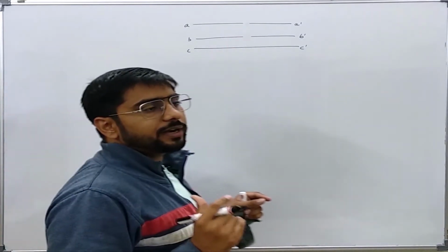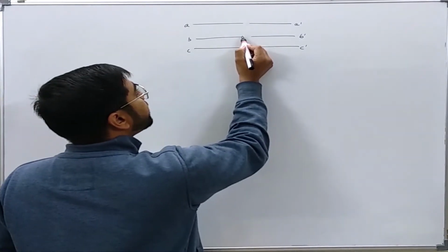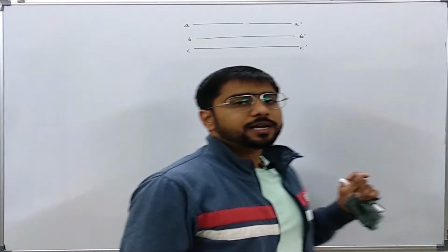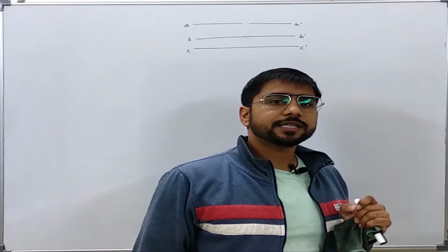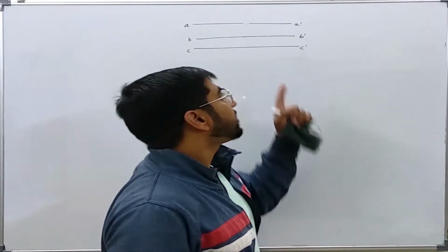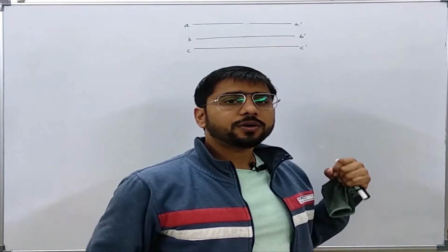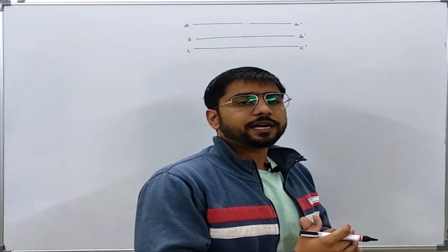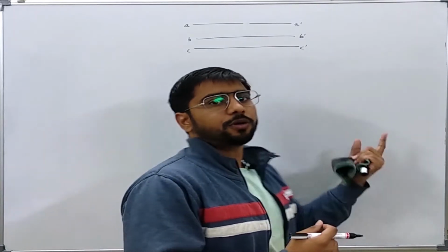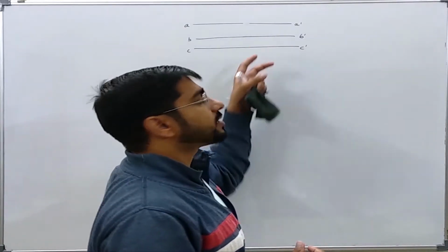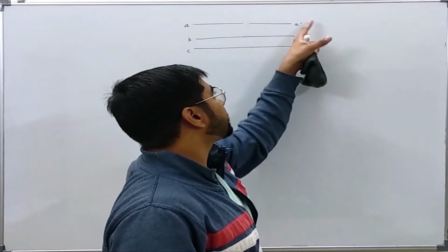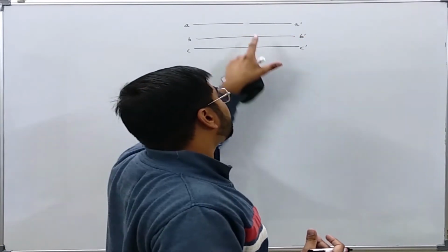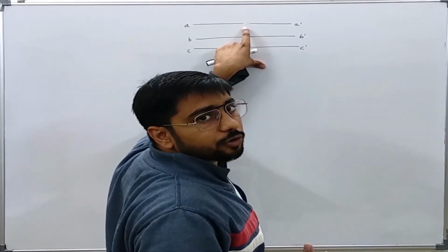So first we will try to see the first case in which only one phase is open, that is one conductor is open. Now this kind of situation can arise whenever, let us say, only single fuse is blown, or we have single pole breakers with auto reclosing facility such that only one pole of the breaker opens and other two poles are not opened because of the fault at, let us say, this point. So this is also kind of one phase open or one conductor open situation.